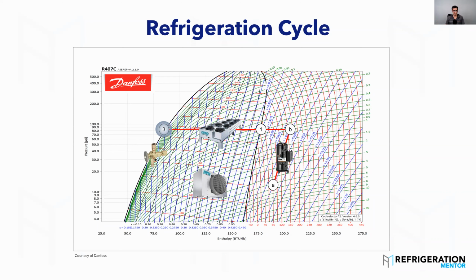And we hit this line. Subcooling will happen, but subcooling's not happening yet until we hit the bubble point. Brendan put it in there. We're hitting the bubble point. Only after that bubble point is when we start to subcool. Right here, just like we talked about before.